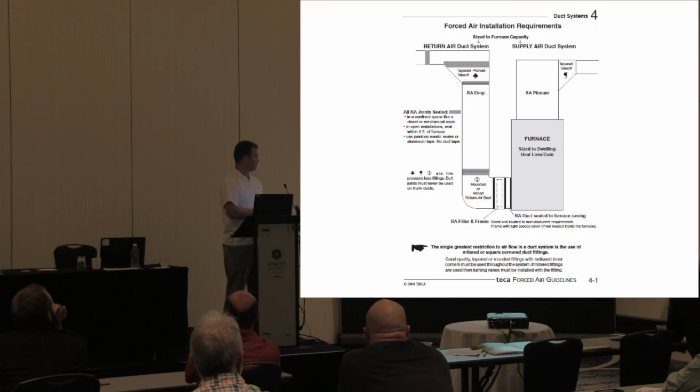Some of the jobs I've seen pictures of, some guys will just oversize the duct a huge amount, like the drop, for example, instead of trying to make fancy fittings, which will help for sure, because there'll be less resistance in that drop. But the more it's tapered, the better it is. Most guys use the tapered fitting on the supply always, because they can buy it from the wholesaler.